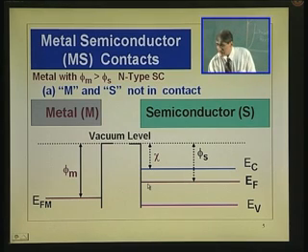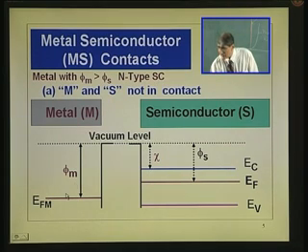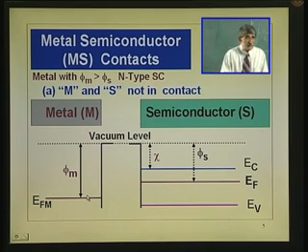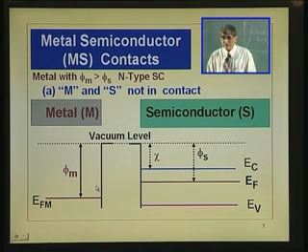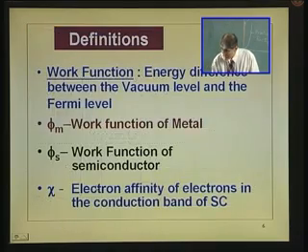So, the Fermi level will immediately equalize, and to equalize the Fermi level, the electrons will move from here to here. In fact, what is happening is you find that there are a lot of electrons here, much higher than this level where there are energies available. So, if there are energies available, the electrons will go and occupy that level. That is what happens. Electrons from this level get transferred onto these levels which are available in the metal. So, once the electrons are transferred, what happens? That is what we are seeing here.